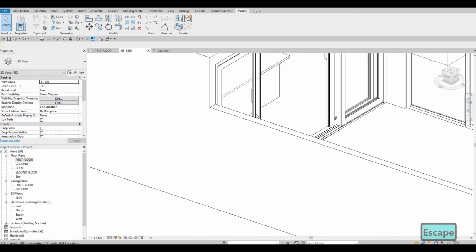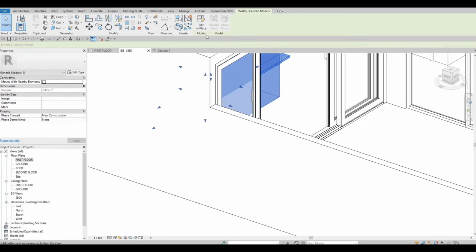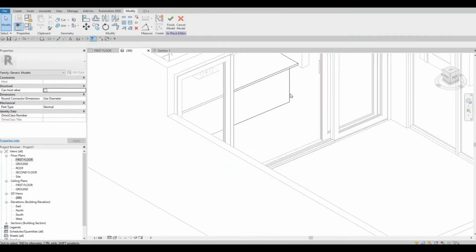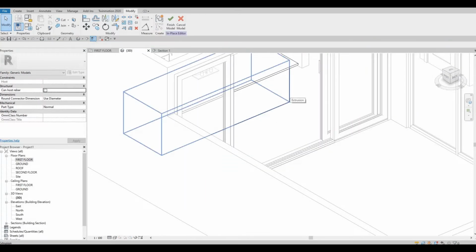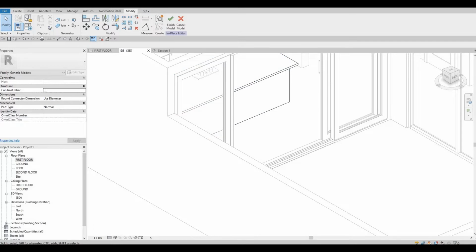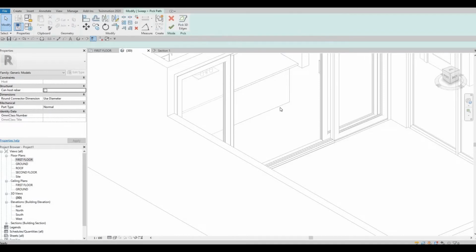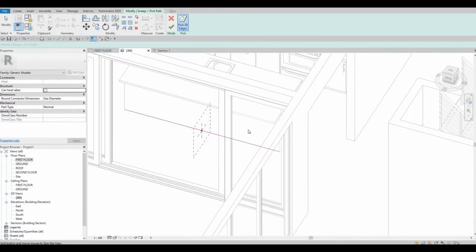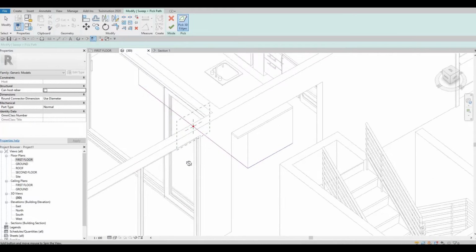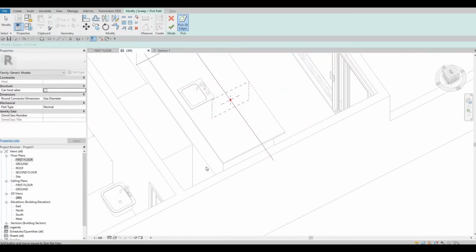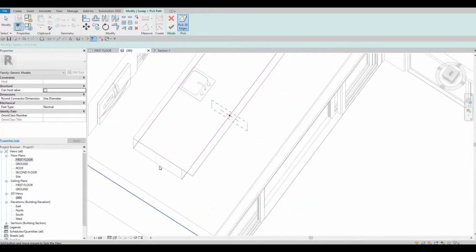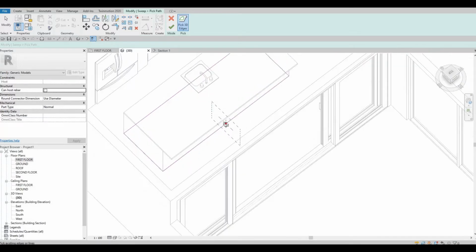And then we're going to have a sweep all around. So click edit in place again, select this, or we could just create, choose void sweep, pick path. We have this one. So you just need to go around here, making sure that you'll see everything. It's very simple like that.